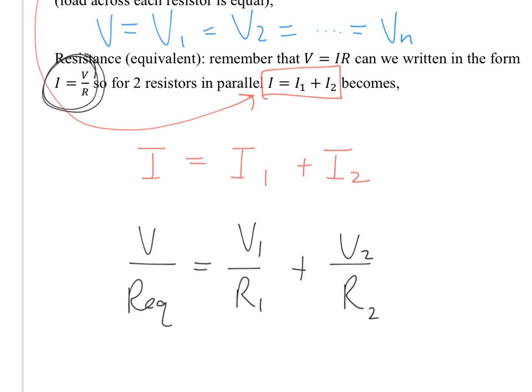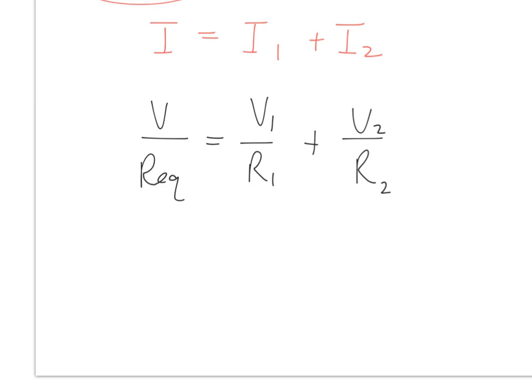I purposely didn't move the slide up too far so you can see the very top. The voltage supplied to each resistor is equal. So that means that I can replace voltage where we see V1 and V2 with just V. The voltage supplied to the circuit is equal to the voltage across each resistor. So those are really all just V now. And then I continue.